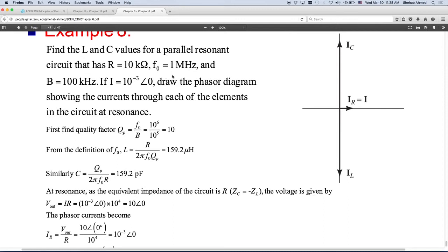So instead of giving you the quality factor now, they give you the bandpass frequency range. Because if they give you a bandpass range, it's an indication of the filter's quality as well, right? If the bandpass is very narrow, meaning you're only allowing a very limited range of frequencies to pass through, what does that say about the quality factor? High quality factor, right? So they can either give you the quality factor or the bandpass frequency range.